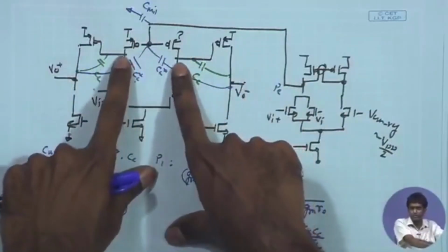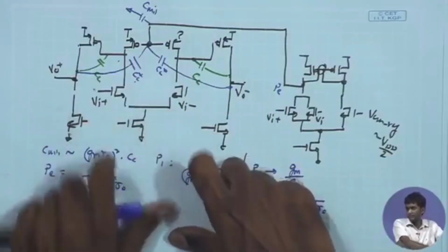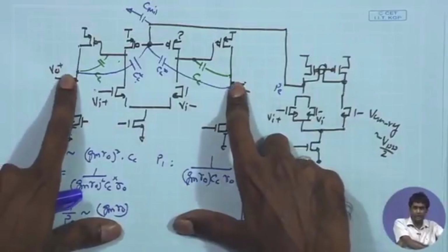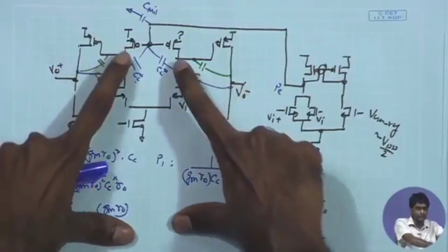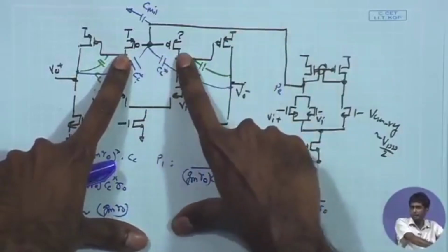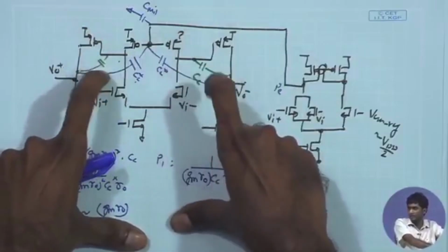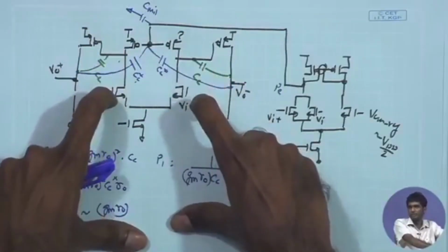You have a well defined voltage over here, which you are setting equal to a desired value. But when you are looking at only the output and allowing the feedback to set the value over here, this is only dependent upon the common mode feedback. It can go low or high depending upon the loop response, and then the first stage can end up being in trouble.